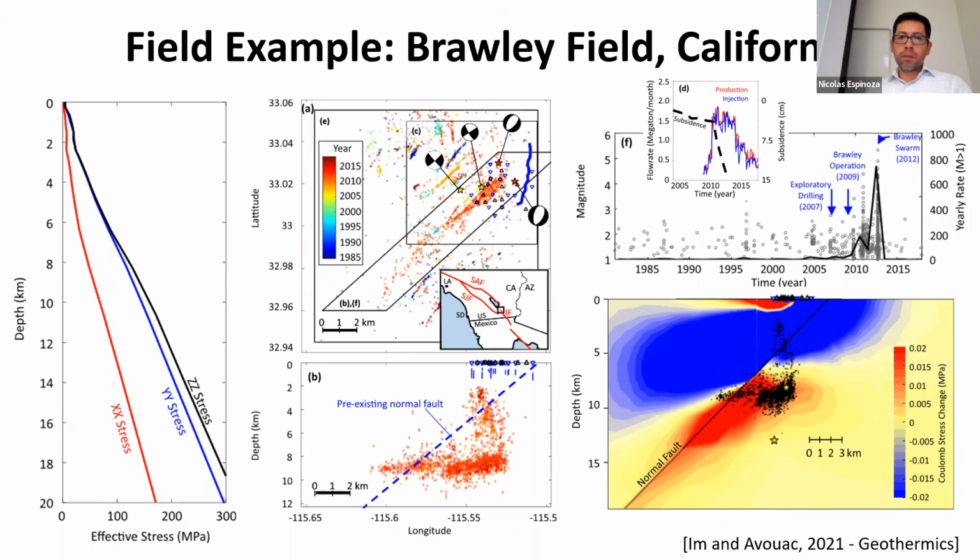Excuse me, do you know if the change in stress regime is predominantly noticed in a certain type of fault as compared to another? Well, I think we're going into one of the slides I have, but I'm going to tell you the answer shortly. Normal faulting will tend to reactivate more faults because what you change mostly is the horizontal stress.